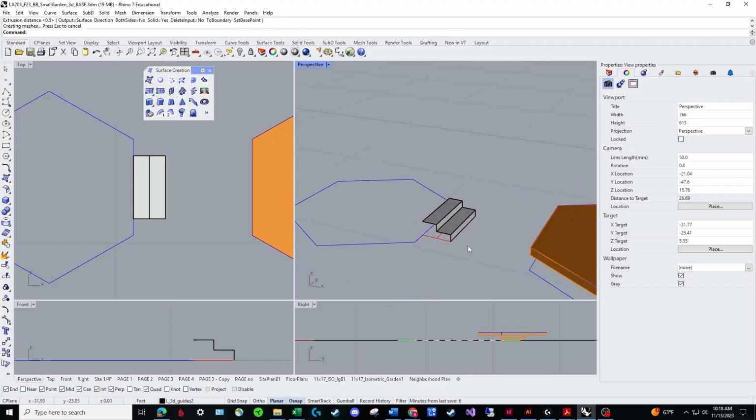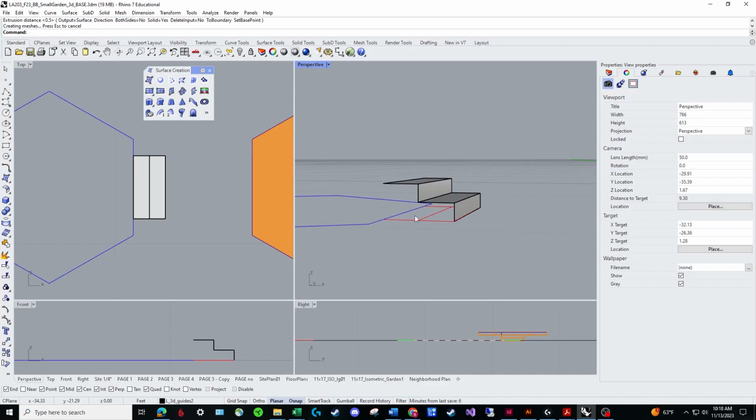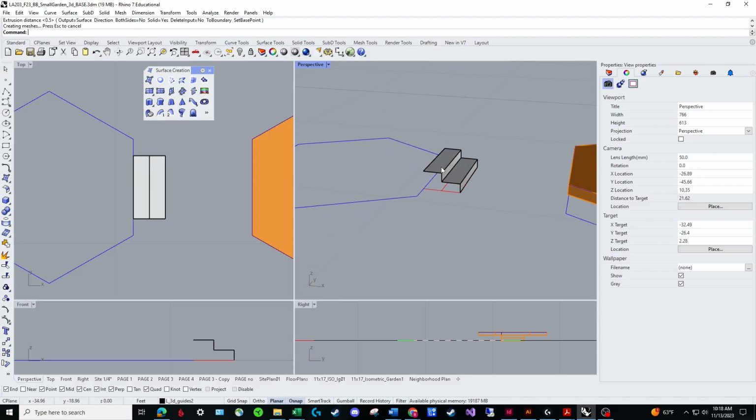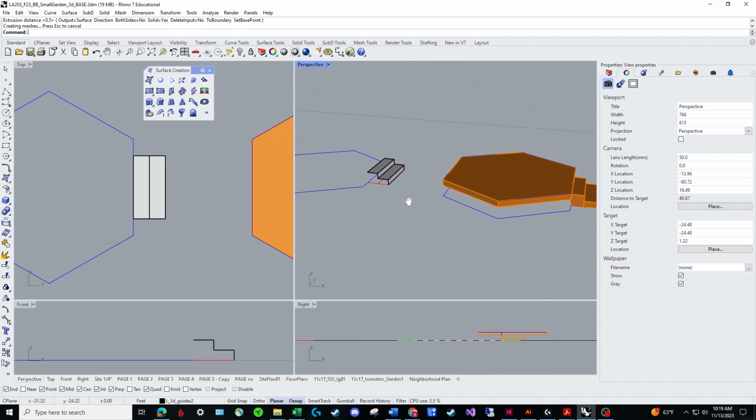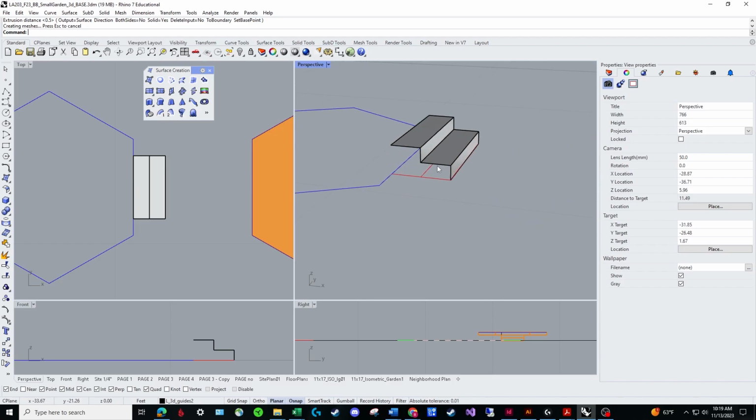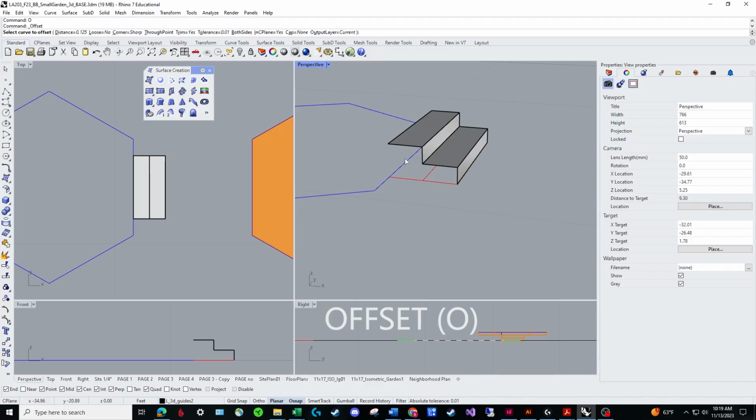One of the things, obviously these stairs are not paper thin. They're going to have some dimension to them, or depth. And I could draw a rectangle all the way around this and just make it sort of flat, like this one looks like, basically. Or I can think, oh, this will probably be like a 1.5 inch, 2x4 or something like that, or 2x6 or whatever it is. And so it'll have a little dimension to it, but it won't be that much. And the way I can do that is actually offset, and I'll offset, I guess I'll just do 2 inches so we can see it.